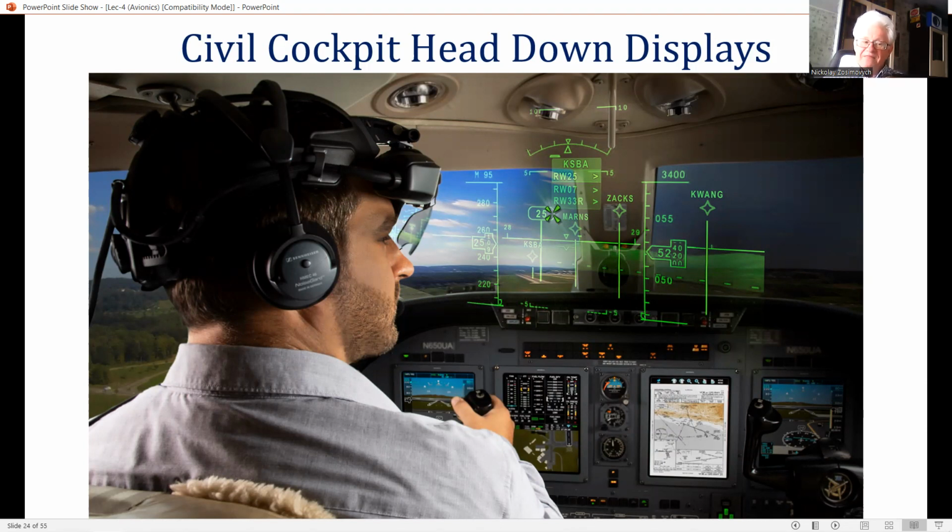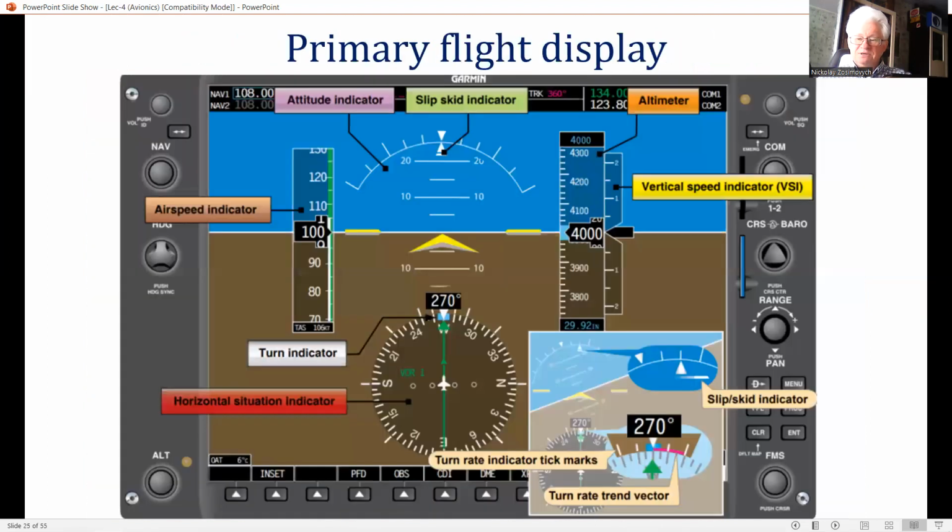The electronic primary flight display, PFD, replaces 6 electromechanical instruments: altimeter, vertical speed indicator, artificial horizon or attitude director indicator, heading or compass indicator, and Mach meter. PFD format follows the classic T layout of the conventional primary flight instruments. And this figure shows a representative primary flight display.